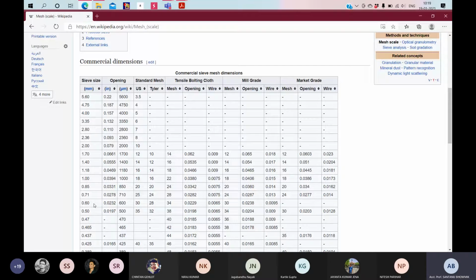So what is this going to indicate? As you are going to get more contact area, the adsorption or desorption will be much more than the earlier case. So when you reduce the particle size, the diameter or the size range, you are continuously increasing the surface area of the particle. And as you increase the contact area with gas, the gas can have a direct contact with the particle, which is not possible for a chunk sample. That's why if you reduce the particle size, the adsorption capacity is going to increase.